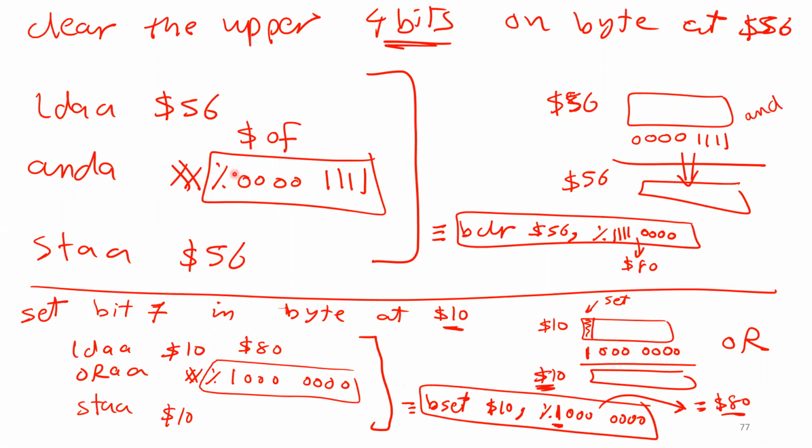Okay, guys. Again, because this is an immediate value, you have to put a hashtag here, okay? And you can put this number in binary, that's why I put % here. Or if you like hexadecimal, you can put 0f this way. But I want to give you advice. To me, both are the same, but you have to be careful, please, guys.